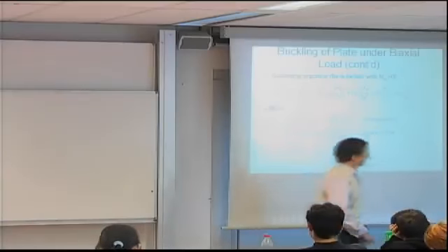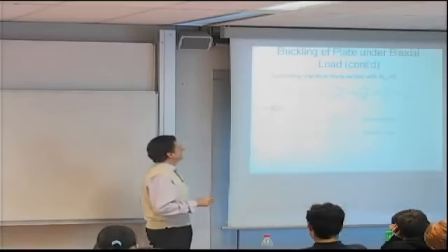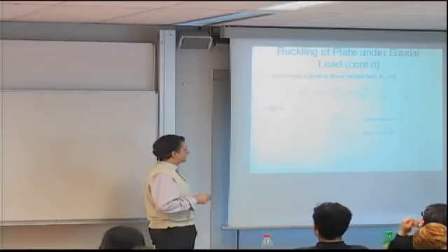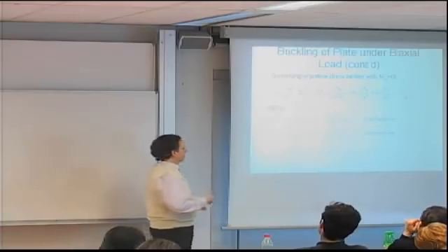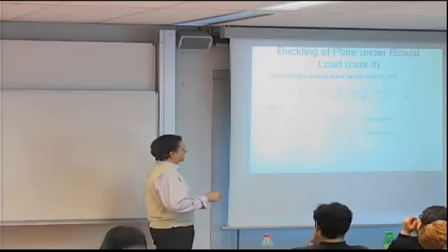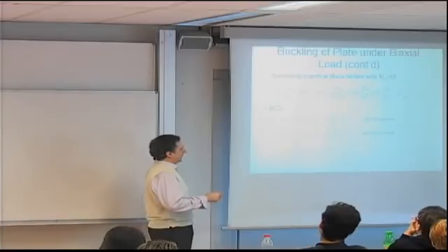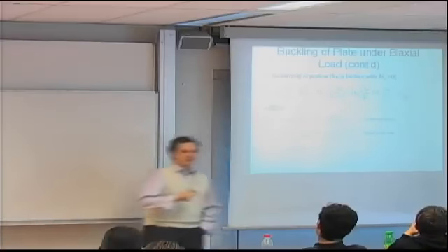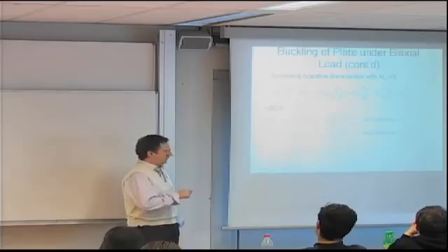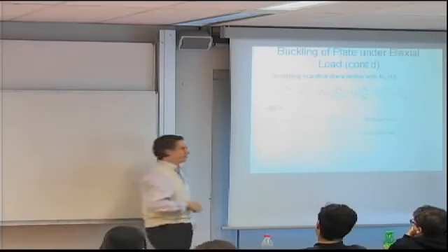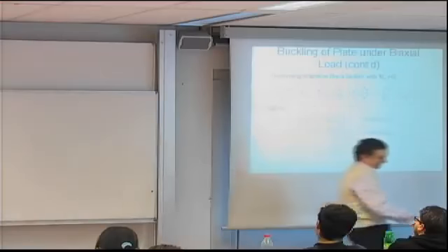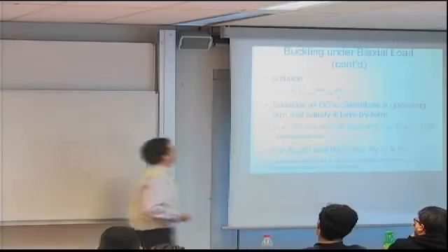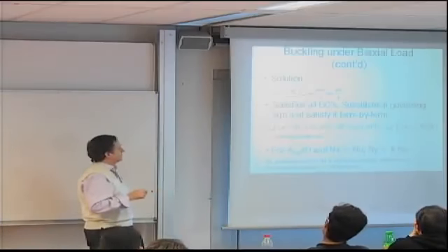We said the governing equation was as shown here, and we are dealing with a simply supported plate which has deflections and bending moments 0 at the edges. Be careful which bending moment is 0 at what edge. For example, the Mx must be 0 at x equals 0 and x equals a, not at y equals 0 and y equals b, because that's the operative bending moment, or the exposed bending moment at that edge, if you will, is the My.